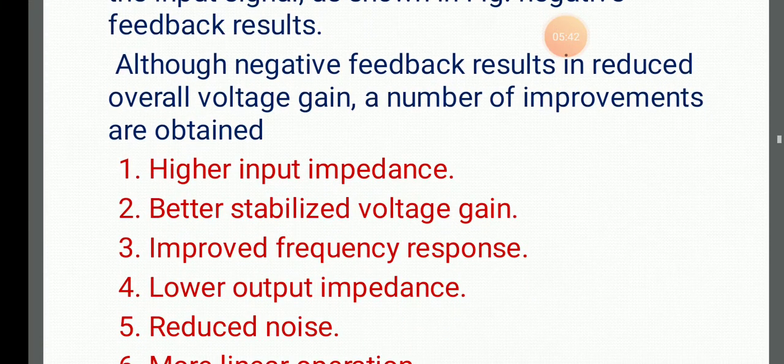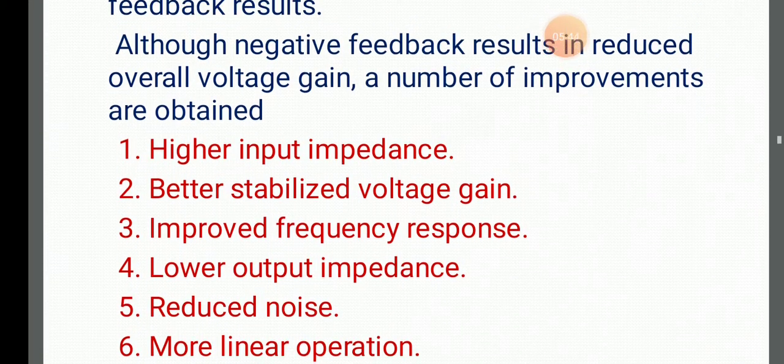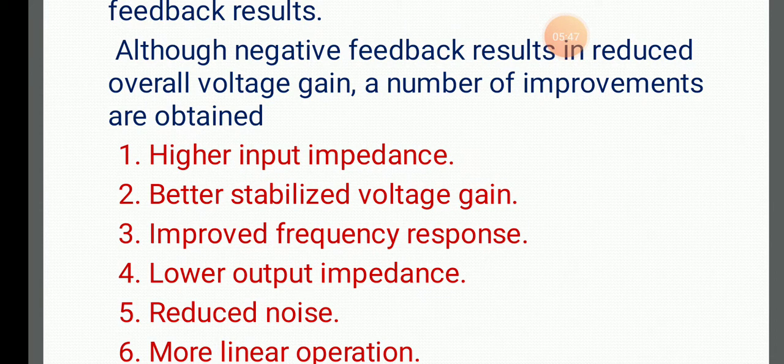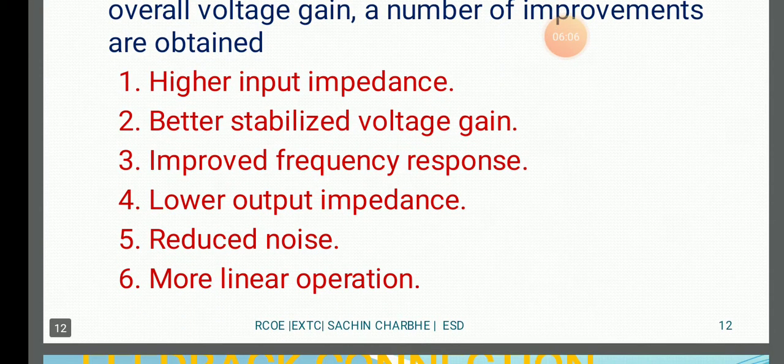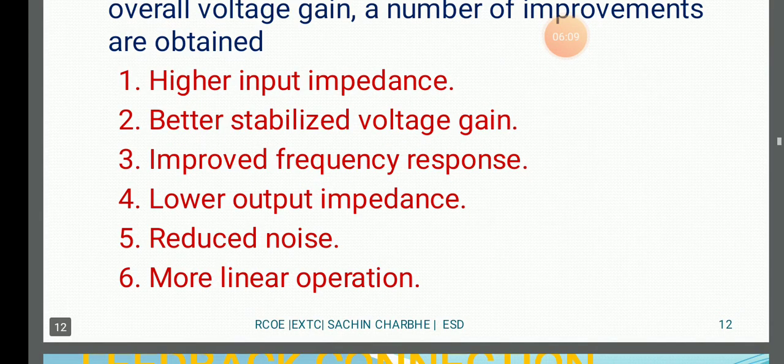These are a few points. There are six main improvements. First, higher input impedance, which we require. Then better stabilized voltage gain: we require the gain, but stabilized. Then improved frequency response. Then lower output impedance: we have to keep the output impedance very low. Then reduced noise and more linear operation.